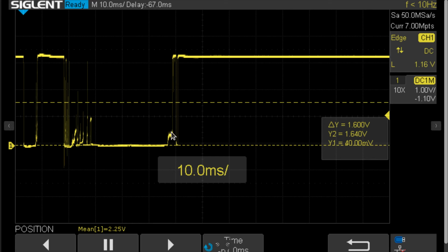And the same thing will happen over here. It'll jump around and it'll go 1 and, well, I don't know, we better wait a little while, aha. And then way over here, it'll count up enough to say it has gone from the 0 to a 1 and stayed there long enough for me to accept that that is the case. And that's how we're going to debounce this thing.